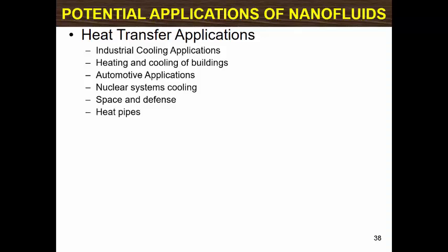Nanofluids employed as working medium for conventional heat pipes have shown higher thermal performance. Recent electronics generate an enormous amount of heat, which disturbs the normal performance of the devices and reduces reliability and expected life. Therefore, an efficient cooling system is one of the most important problems in designing electronic components. Since nanofluids have high thermal performance and can flow in microchannels without clogging, combined microchannel heatsinks with nanofluids have potential as the next generation cooling devices for modern electronic components.